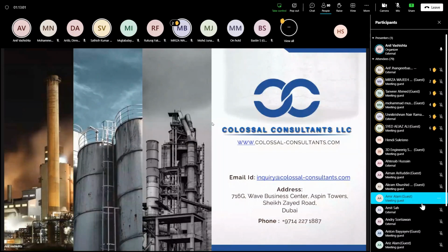Exactly. What we do in general is, when we start the failure investigation, we have 5 or 6 different probabilities of the failure. We note down those probabilities of failure, and during the course of study, one by one, we overrule the ones which are not applicable, and we find which one is the most applicable case or probable cause of failure.